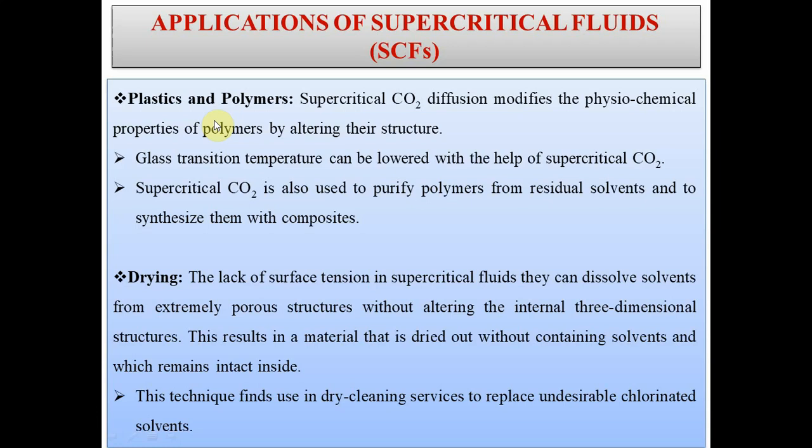Application of supercritical fluids in plastics and polymers. Supercritical CO2 diffusion modifies the physicochemical properties of polymers by altering their structure. This is a very important property. Glass transition temperature can be lowered with the help of supercritical fluids, carbon dioxide. Supercritical carbon dioxide is also used to purify polymers from residual solvent and to synthesize them with composites.